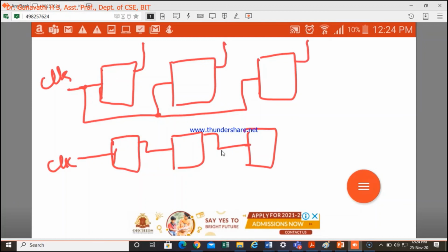So now, what is the delay in this? The delay of this counter. If it is sequential and synchronized with respect to the clock, everything is working at a time. So the delay of one flip-flop, which I don't know exactly, will be in terms of some nanoseconds, is the delay of this entire circuit, because the same delay applies for everything here.